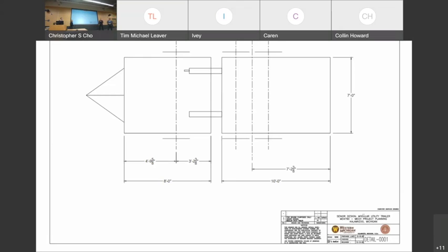So this research basically got us to the conclusion of a general rule of a 60-40 split between the front and rear sections of the length of the trailer, based off the axle location. So basically you have 60% of your length here, such that you can have more weight loaded onto the tongue of the trailer and onto the hitch, versus having any sort of load pulling onto the rear end here that would cause handling issues as we haul the trailer.